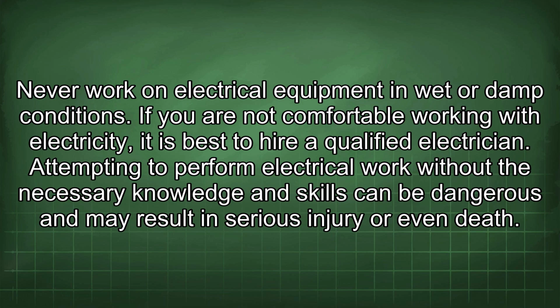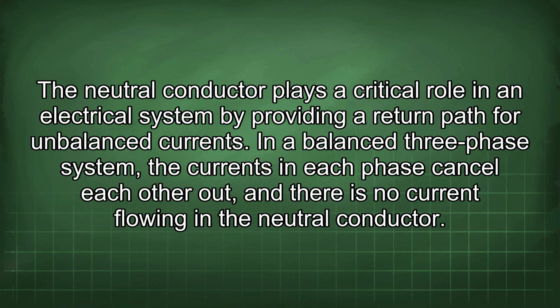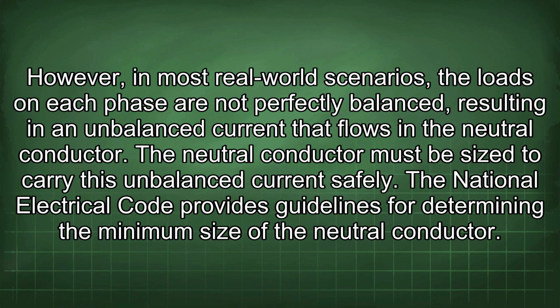The neutral conductor plays a critical role in an electrical system by providing a return path for unbalanced currents. In a balanced three-phase system, the currents in each phase cancel each other out, and there is no current flowing in the neutral conductor. However, in most real-world scenarios, the loads on each phase are not perfectly balanced, resulting in an unbalanced current that flows in the neutral conductor. The neutral conductor must be sized to carry this unbalanced current safely.